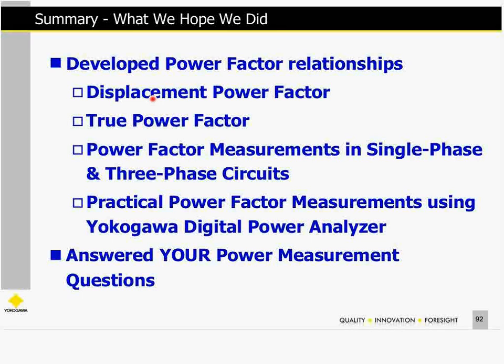We talked about displacement power factor, so if you're dealing with true sine waves, like in our power utilities, we can look at the displacement as cosine of theta. But for all of our power electronics applications that we're doing today, we got to look at a true power factor. And we gave you some examples of some power factor measurements in a single and 3-phase circuit.